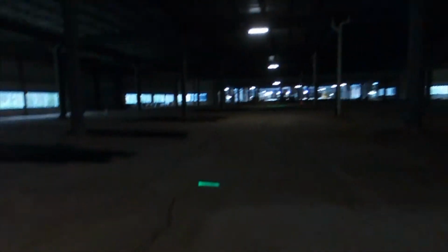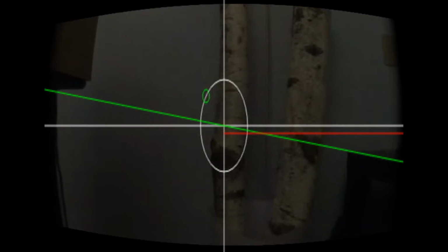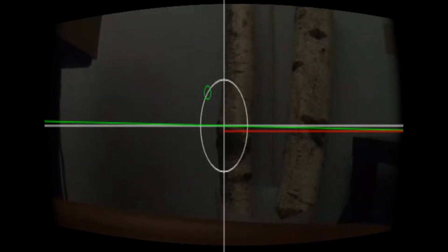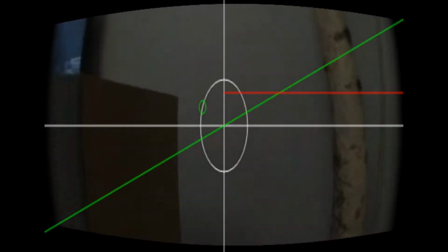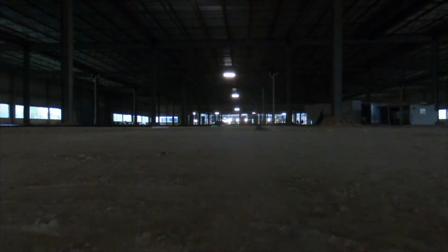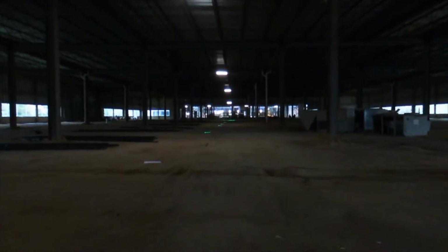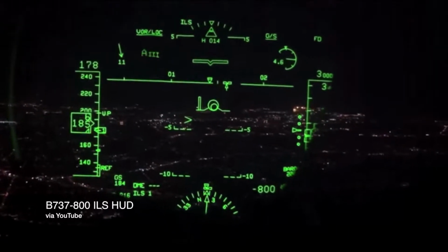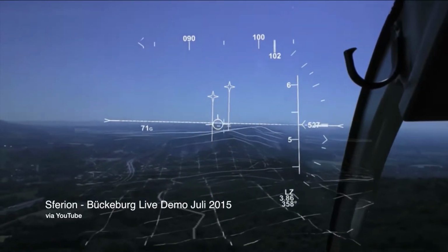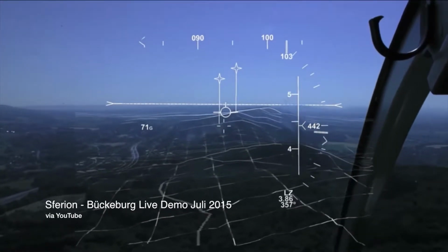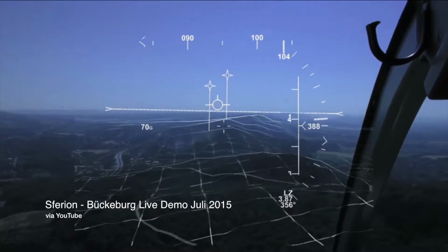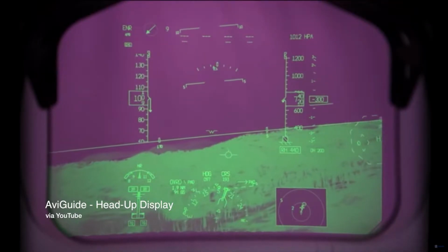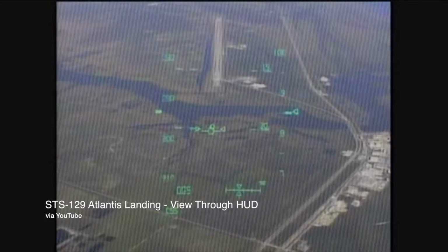We found head tracking in particular drew so much of the pilot's attention that it added its own layer of difficulty, and we ended up making it optional. The early versions of the HUD at the time were, while helpful, did little to make us better pilots. My test pilots and I were extremely crash prone, and we quickly learned the Bebops were as delicate as flower petals. I started doing more research on information display in situations where safety is a concern and where there are high speeds. It led me to various pieces of research by NASA and others on head-up displays for everything from commercial airliners to helicopters to the space shuttle.